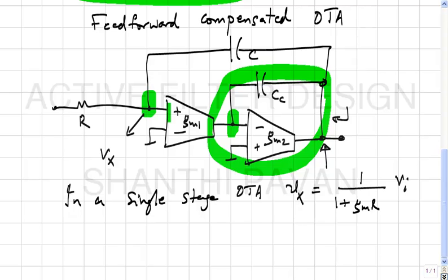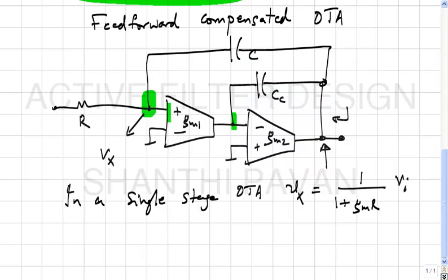In other words, you can think of that as an integrator itself, correct? If I just only showed you this picture, you would immediately say it is a part of an integrator built using a single stage transconductor GM2, isn't it? And with an integrating capacitor Cc, right? So, which means that this node potential must also be close to 0. Now, can you comment on the voltage across C and the voltage across Cc given these assumptions?